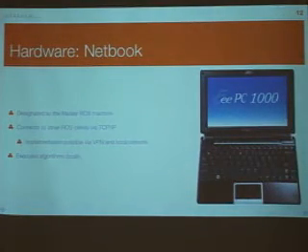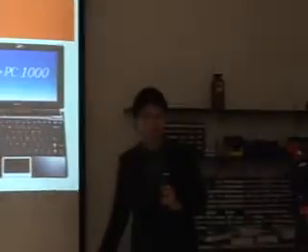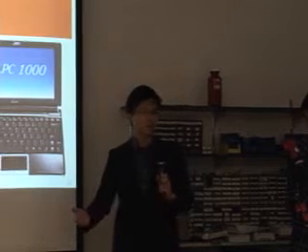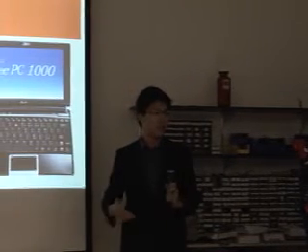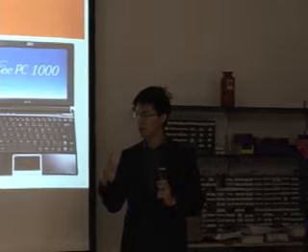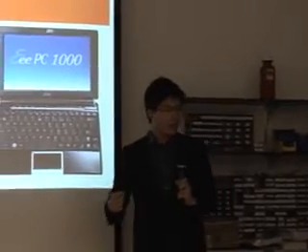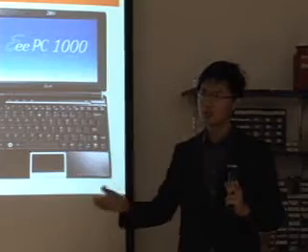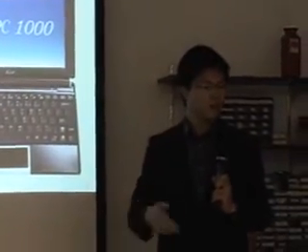And sadly, the most important part of it all is this gigantic laptop on top of the robot. We originally wanted to shoot for a netbook that we could put into this docking bay underneath, but we made do with what we had. A typical coding environment is that we have this master laptop placed upon the Turtlebot platform, and other ROS workstations running Ubuntu. All these laptops connect to one private network, so they all have statically assigned IPs, and communication over the ROS clients happens over TCP/IP.